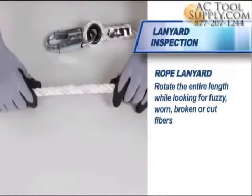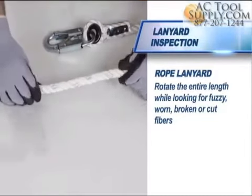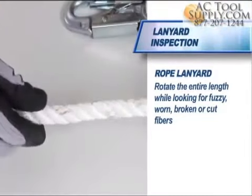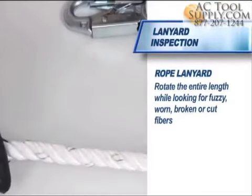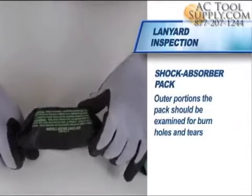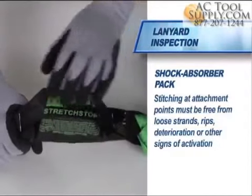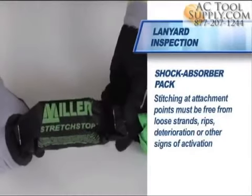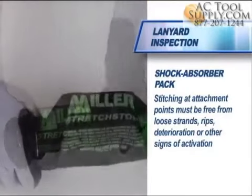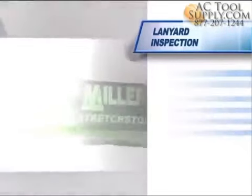When inspecting a rope lanyard, rotate the entire length while looking for fuzzy, worn, broken, or cut fibers. Diameter of the rope must be uniform. Outer portions of the pack should be examined for burn holes and tears. Stitching at attachment points must be free from loose strands, rips, deterioration, or other signs of activation.